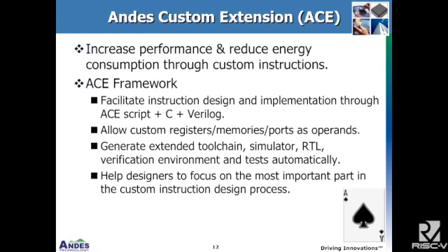The framework facilitates instruction design and implementation through some ACE script and some C statements and Verilog statements. And we also allow our customers to add new custom registers, memories, and ports as operands. And the framework will generate the extended toolchain, simulator, RTL, and verification and tests automatically. This framework will help designers focus on the most important part of the new instruction design. And the framework will just take care of most of the tedious things for the designers.